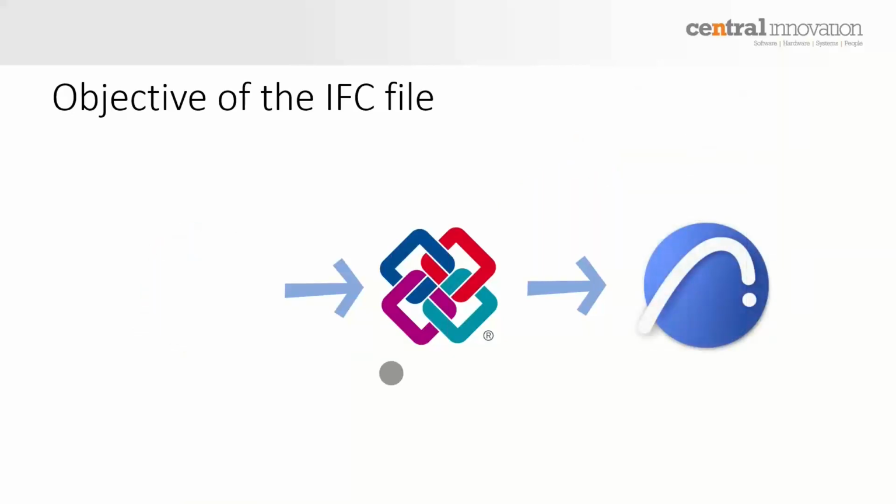Now, within the context of a design handover, this changes a bit, because now you actually do have knowledge of which software will be communicating with which other software. That could be Revit, which is very popular and very common nowadays, but it could also be something like Vectorworks or Allplan or any of the other authoring tools out there. The key difference, again, is that the IFC that will be doing the exchange can be and should be calibrated so the translation between the two pieces of software is optimized.